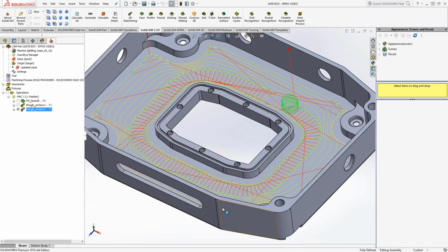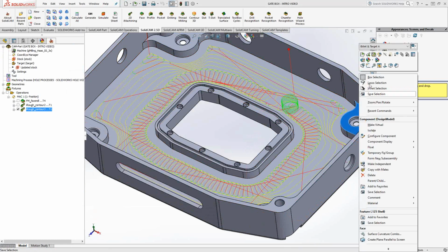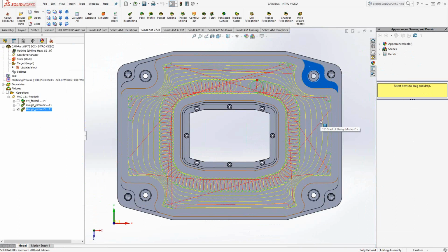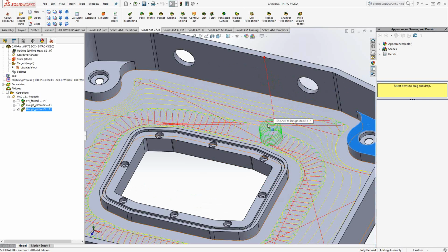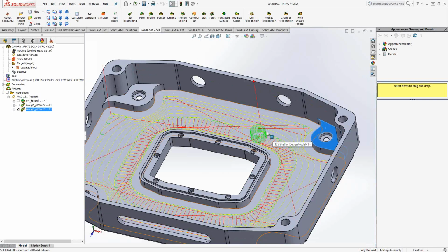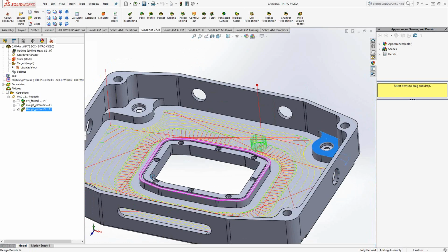And let's take a look at that toolpath. So a little something different is going on here. Because there's an island, it can't exactly do that full morphing spiral that we saw with the previous toolpath. It actually needs to add this separation channel. And that way it can do a better job of doing the morphing spiral. You can see that there. Okay, once again, it does have the morphing, the helical entry, and it does have minimal retraction motions.